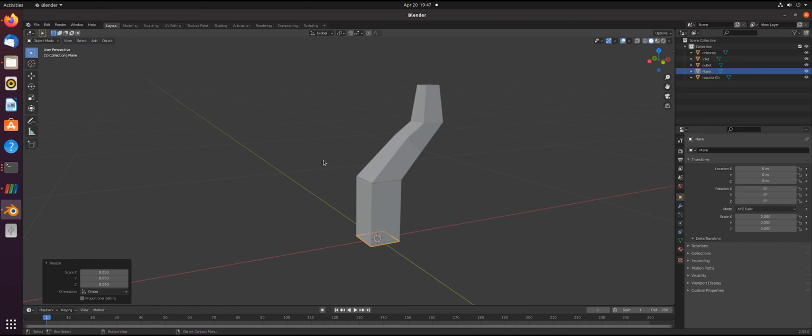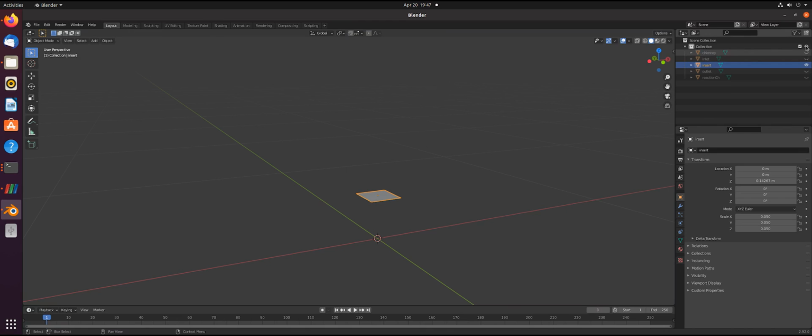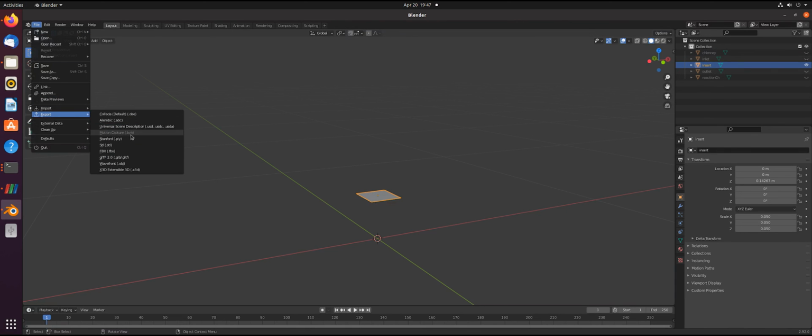The plane is now in the same position as the inlet. For the particle insertion, it would be handy if the insert plane would be somewhere in the top third of the reaction chamber. With the keyboard keys G and Z, I can move it along the Z-axis. The plane should not be placed directly on top of the reaction chamber because the particles need some space to be generated without being in contact with the wall. At a third, it should be good here.